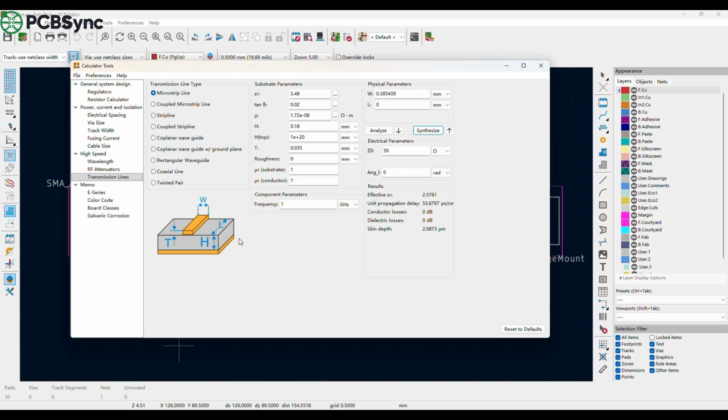Today, we did four things. First, we built a 4-layer RF stackup. Second, we set the thickness. Third, we entered the DK and DF values. And fourth, we completed the 50-ohm calculation. If you plan to work on ESP32, Bluetooth, Wi-Fi, LoRa, and so on in the future, this stackup will meet the needs of most projects.